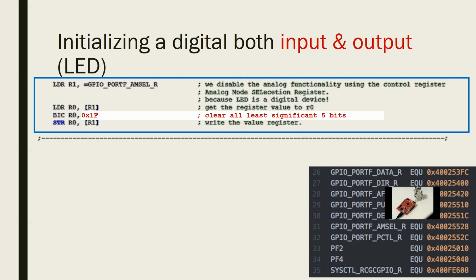But when you make that selection, digital devices which provide very low current and low voltage values will not function properly. That's why you decide what you are going to connect to which pin. If it is a digital device, you have to tell the card beforehand so that the card's necessary connections will be configured accordingly. Is this an explanation for you?